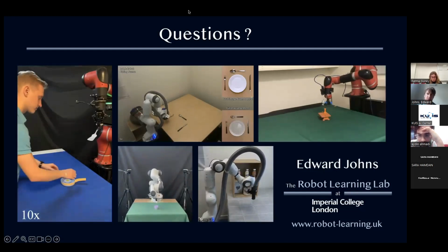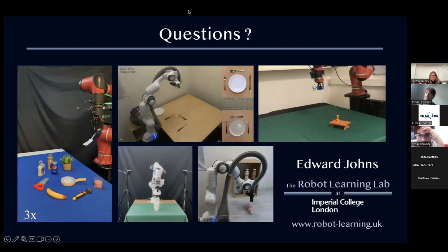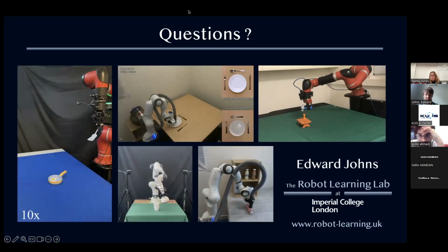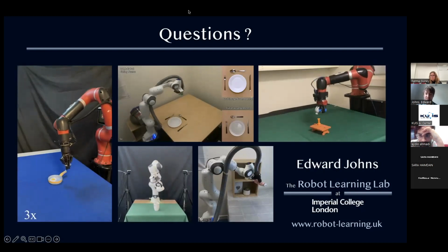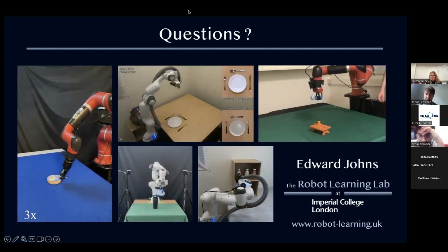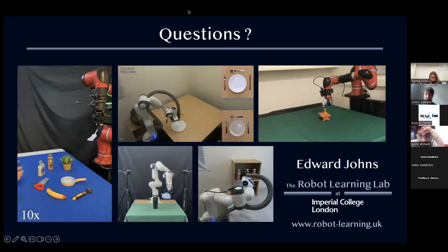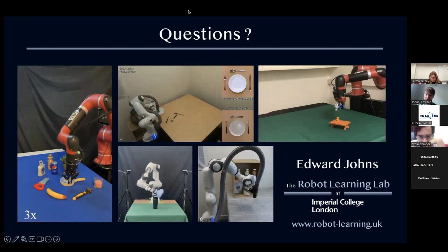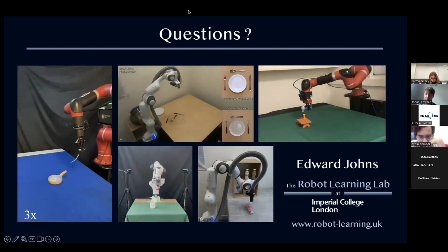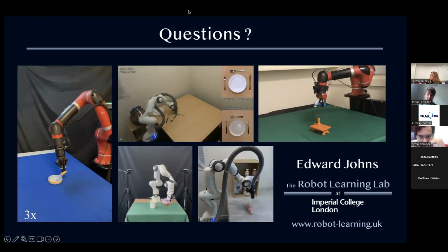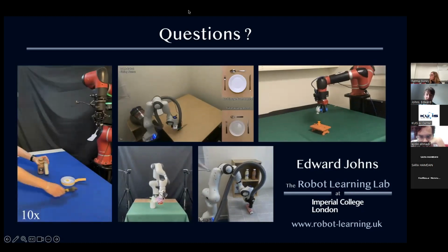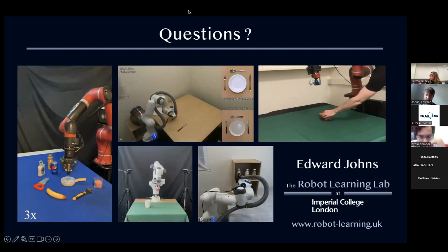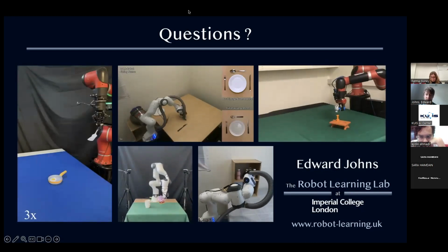as opposed to an end-to-end neural network, which has to make predictions at every frame that the robot sees. It has to make a prediction about the instantaneous action the robot should be taking. Once you approach it from the pose estimation perspective, it becomes more efficient, because as long as the object doesn't move, the robot just has to move to the object's pose. It doesn't have to predict complex trajectories. So by reducing the search space of the robot to a pose estimation problem, that's one way we get this efficiency.